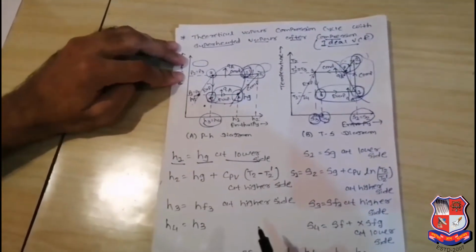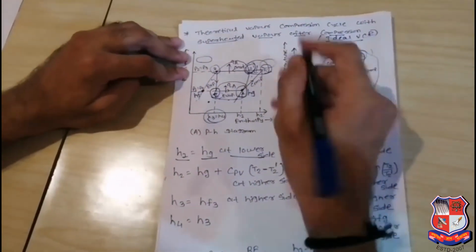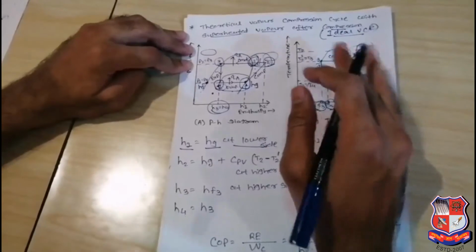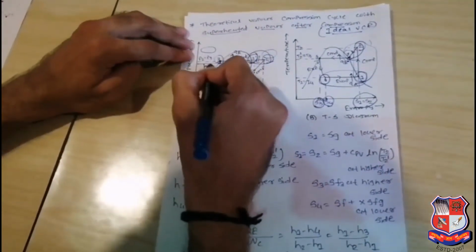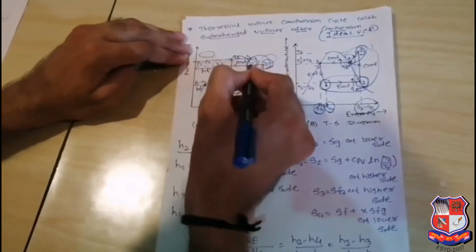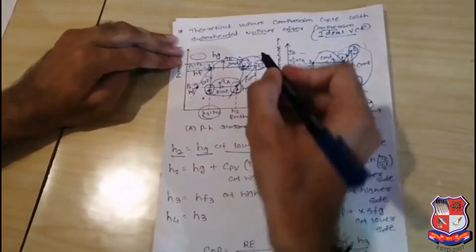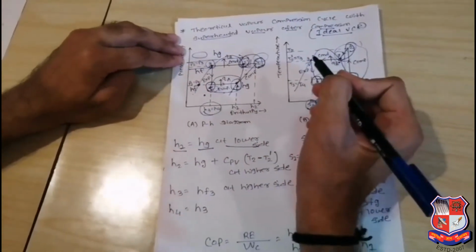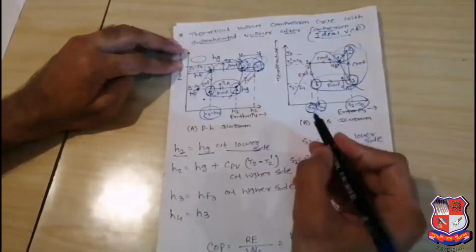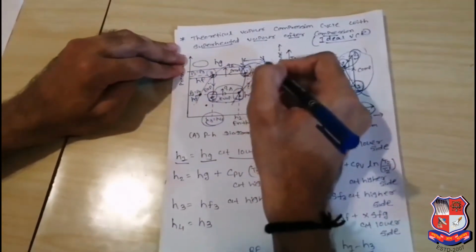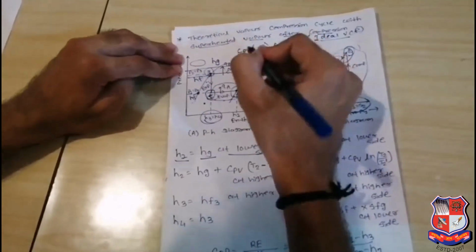Now the second point is in the superheated region, and in the superheated region dryness fraction is not present. So at that time how do we consider it? You just consider first, here to here, that will be Hf, here to 2 dash point, Hg, the enthalpy of the vapor, but we require H2. So how is it considered? At that time you just consider that much distance. Here vapor is present, so specific heat of the vapor is considered into temperature difference, maximum minus minimum.